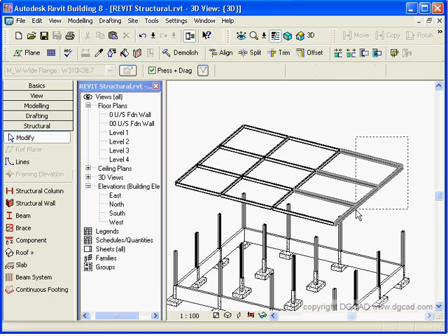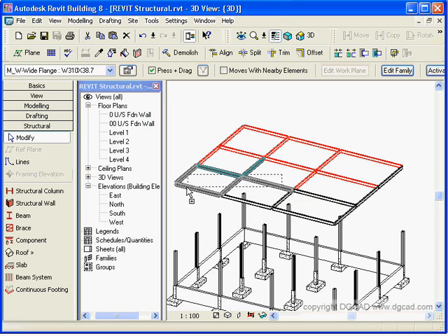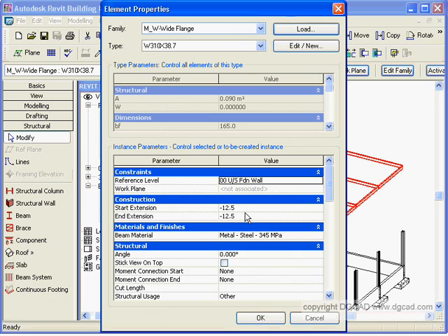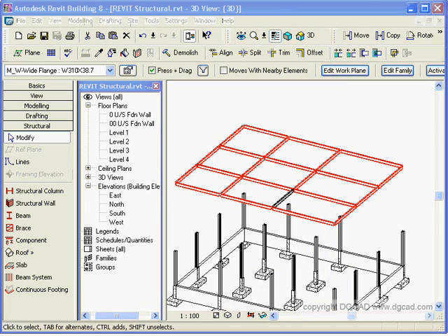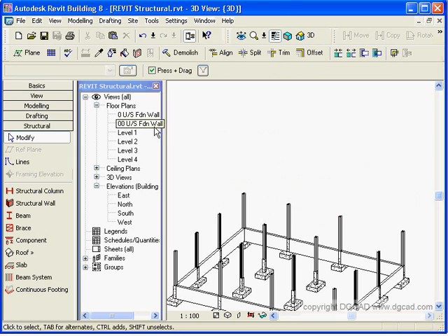Okay, we need to grab all these beams, interestingly enough. Something went wonky with our elevation there. Check the properties of that, and it is reference elevation, start elevation, and extension, beam angle. And I think our problem there was when we created that we didn't set our correct level. So I'm just going to hit delete. We're going to try that again.